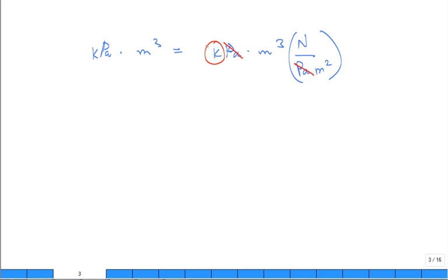All right. Now, can I get rid of meter squared? And then what is a joule? Is it a Newton times a meter from your memory? It sure is. And so the meter goes, the newtons go. I'm left with 1 kilojoule. 1 kilopascal times a meter cubed is 1 kilojoule. I'll use it a lot throughout this semester. So unit conversion is pretty fast then.